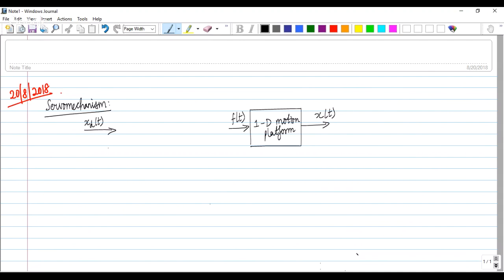That's open loop control. But on the other hand, you tell me to move the platform by a very specific displacement. Let's say you tell me to move the platform by 10 centimeters. So that's my desired displacement. So what I do is I measure the actual displacement using a sensor. Then we take the error in the displacement and pass it through a controller, okay?